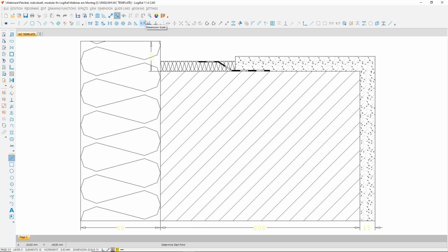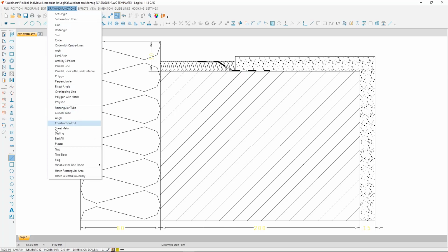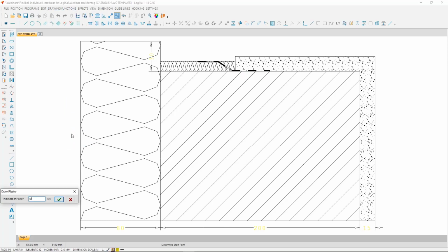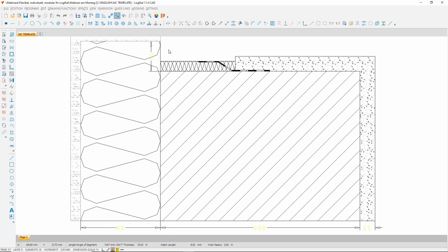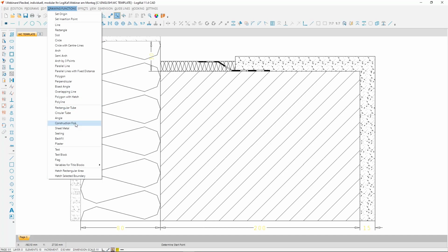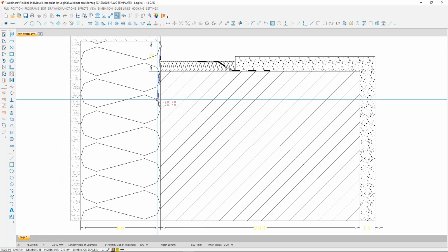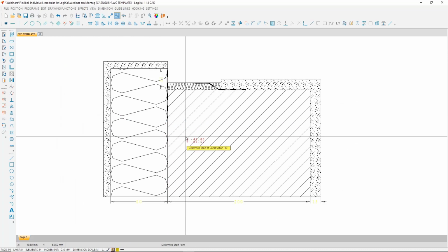I prepared here an almost complete wall connection. You can see here the inner wall and the outside insulation or the inner foils. So the outside plaster and the outside foil are still missing, and I can complete both here with an extra function for this. And with few clicks, it's ready. The same for the construction foil here. And our wall connection is ready.